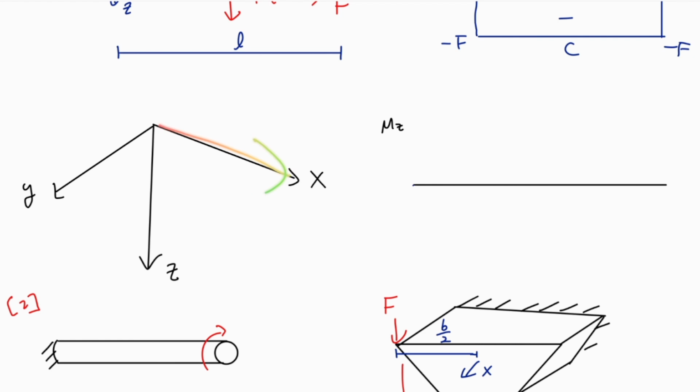We know that everything has to transfer in the x direction, since the x direction is always our axial direction. If I have a force in the z direction, and we go to the x direction, the z direction's force crosses this direction and generates a moment like this, which, if you do the right-hand rule, with the y direction, is the positive moment in the y direction.